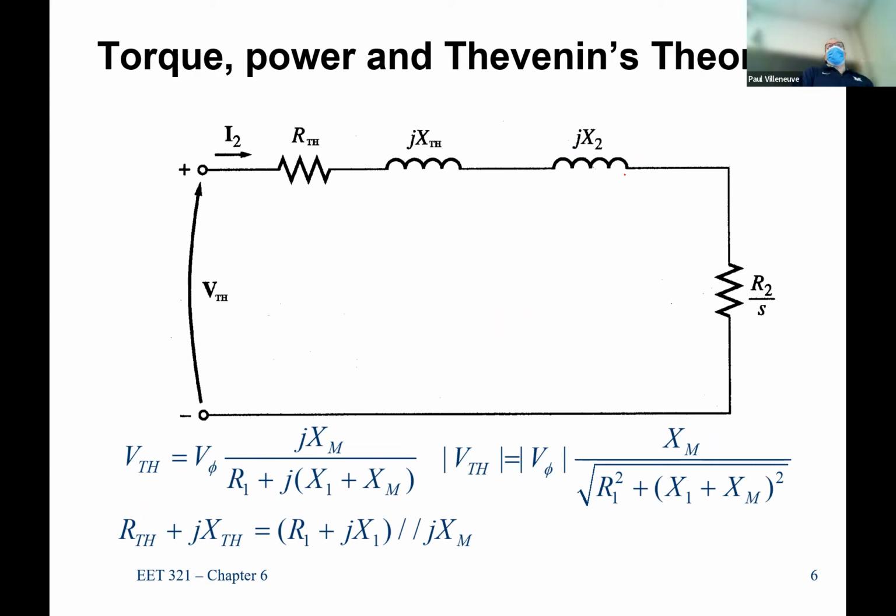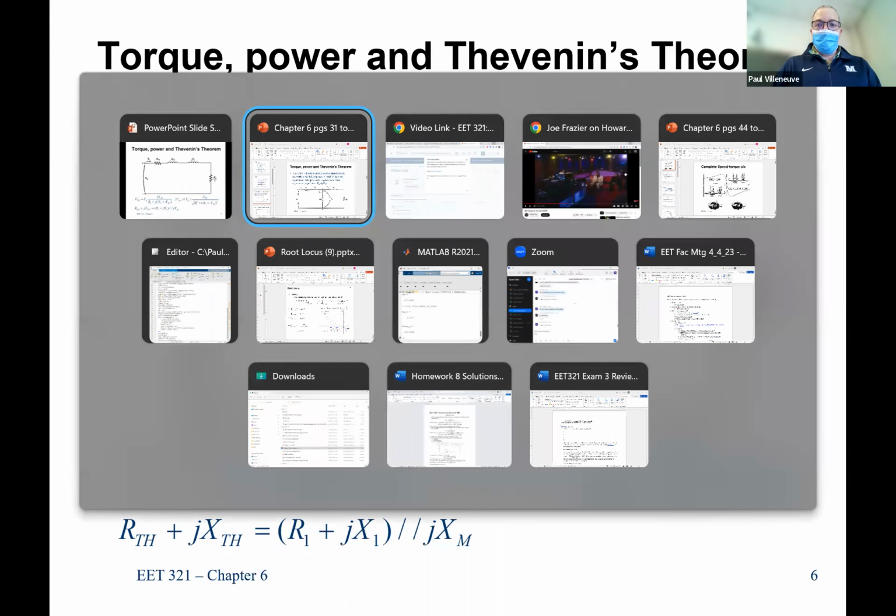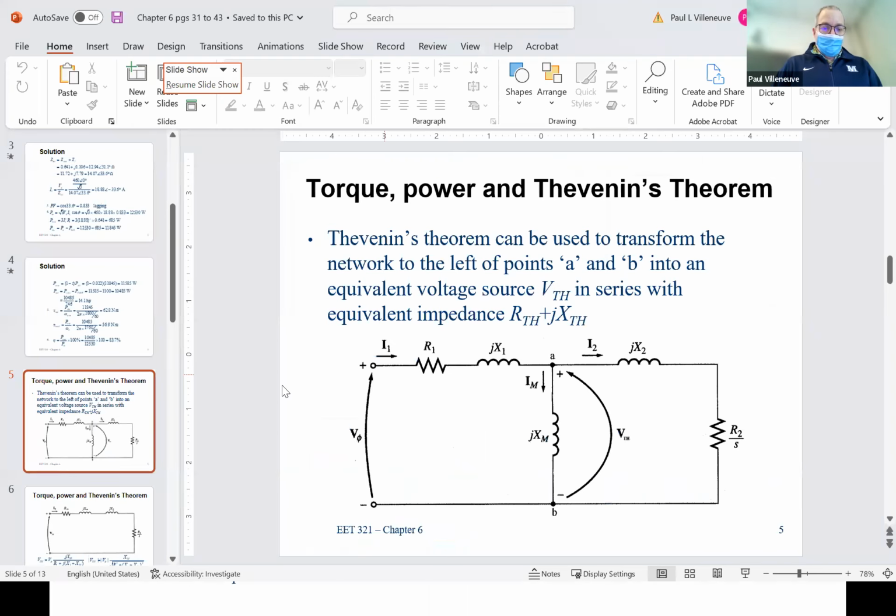So when you're doing Thevenin equivalent, go back to your circuits class, which says you open circuit and you look for the elements, whatever you're trying to replace it with. I remove the load, that's just a load. I set that aside for the moment, and then I do my calculations to solve for V open circuit and Z Thevenin, okay? If you don't like drawing it that way, where's whiteboard? I don't see whiteboard, so we'll have to bring up whiteboard.